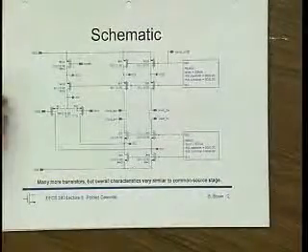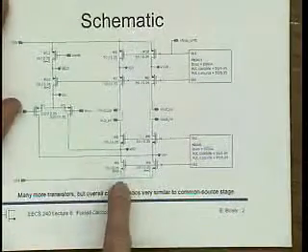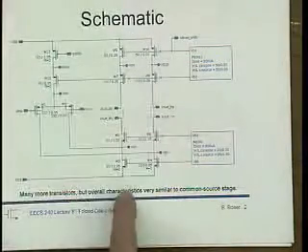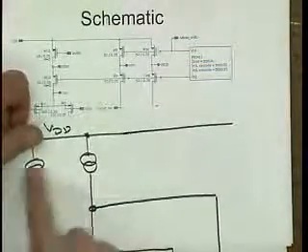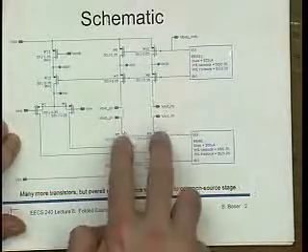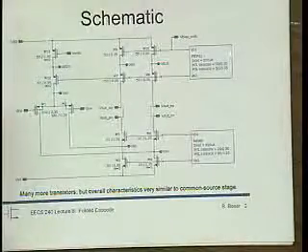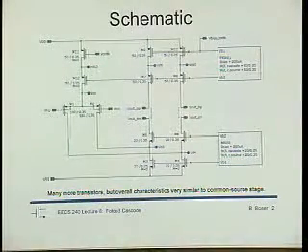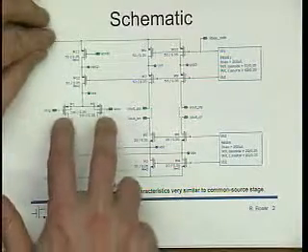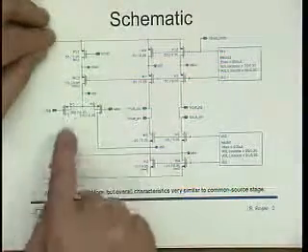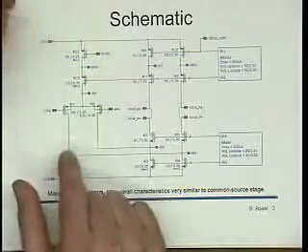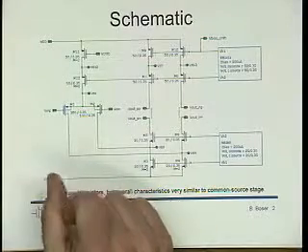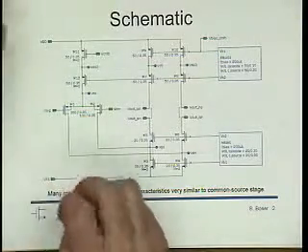So now here everything's upside down, right? Here is the tail current source. Then these are really the mirror current sources, that's these two transistors. Here are the cascodes, and here is the other current source. Okay? And this one, of course, has a PMOS input. The transconductance of this overall stage is simply the transconductance of the input differential pair. So it's really exactly the same thing as we had for the common source stage, right? It's still just a transconductor.